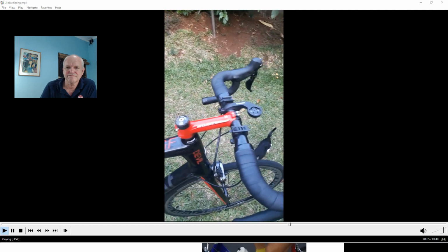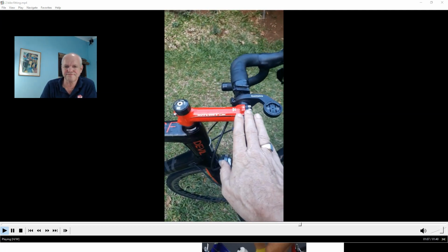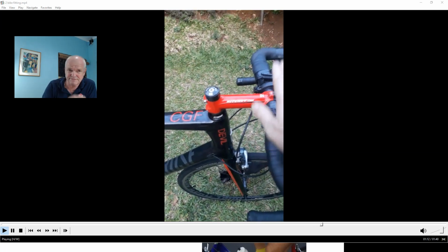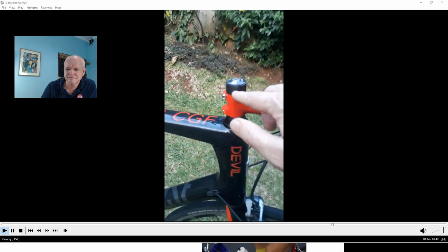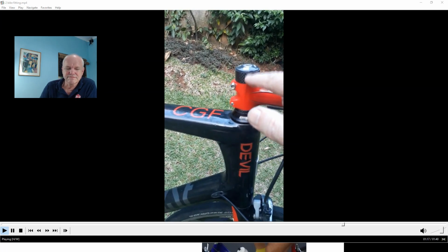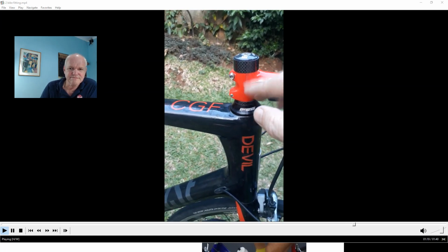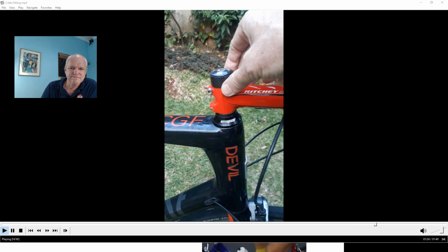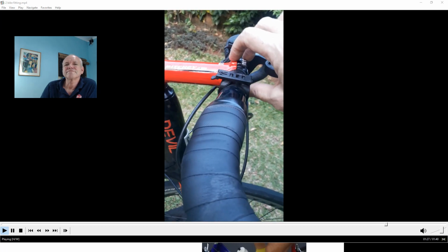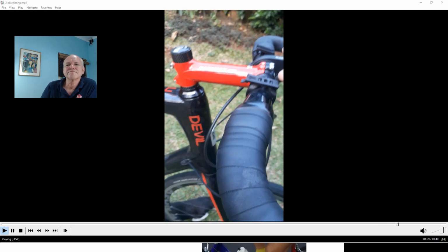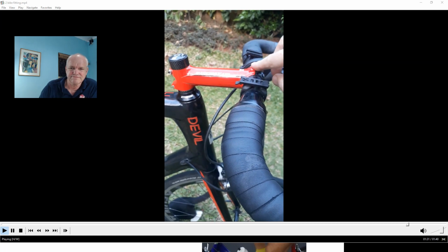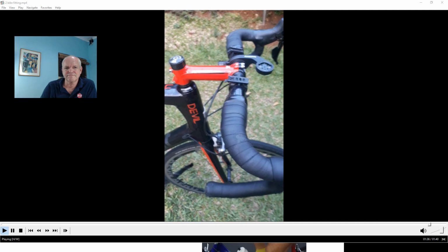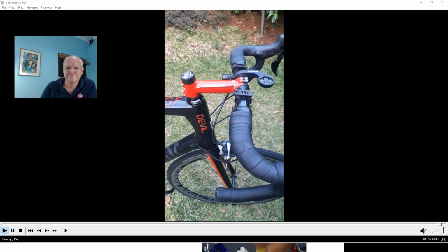And at the end, you find the right position of your handlebars, where you can move it up and down by number one, these rings. I'm in a very low position, but I could move down that ring, then the whole handlebar is going up. Or I also can flip the stem, and I have the low position, then also my handlebar would come up a little bit. So these are the main points you should consider.